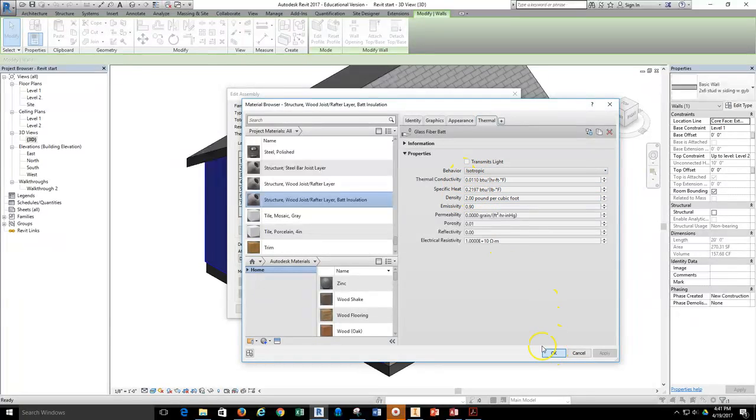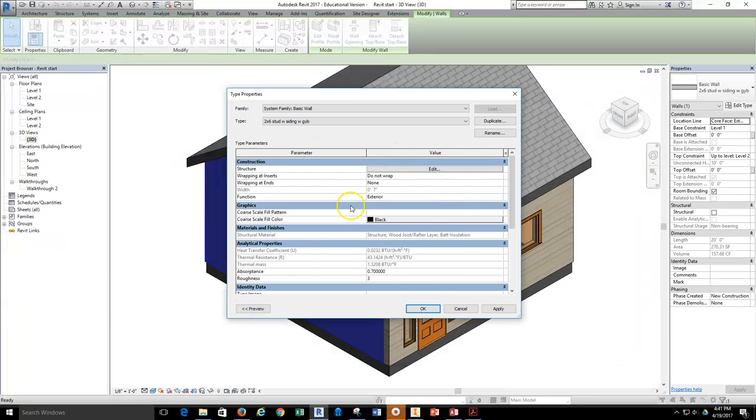Looking at that, I then headed back out of the information here and come up with that there's a thermal resistance or an R value of that wall of 41.14. Thinking that through, that this is a 5.5-inch stud cavity with batt insulation, there's no way that that can occur when R19 insulation is fairly standard for a 5.5-inch cavity in a wall.